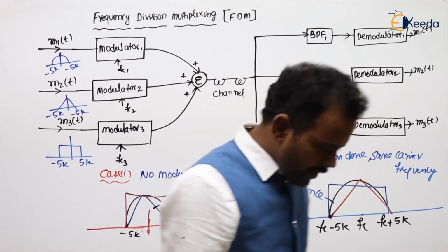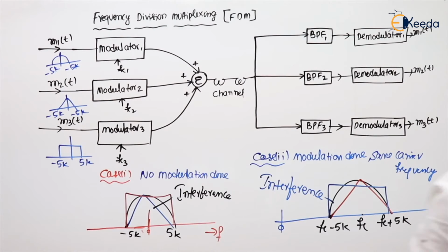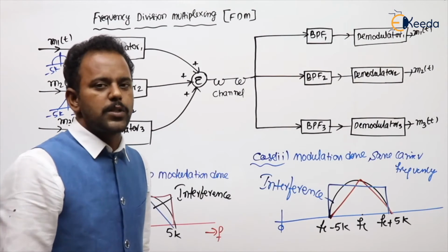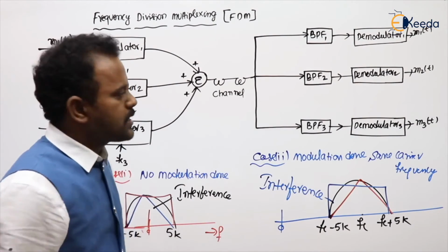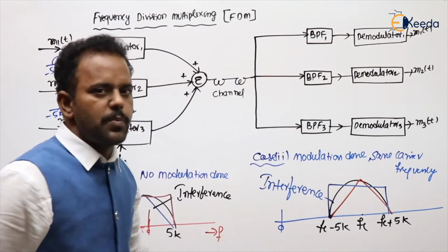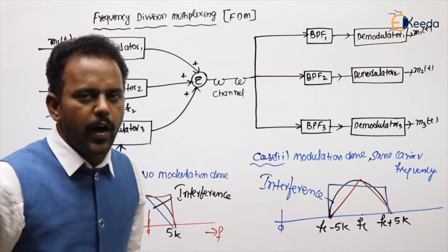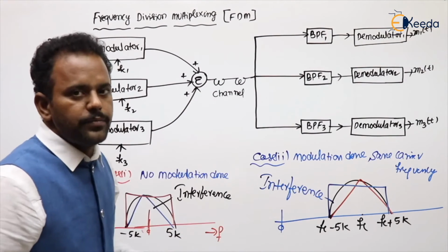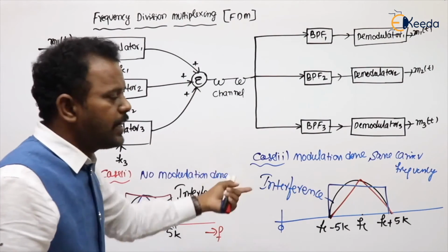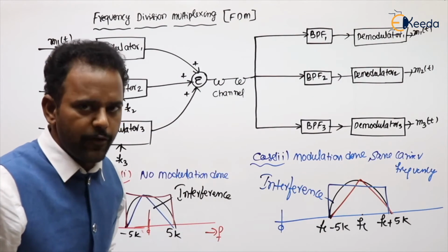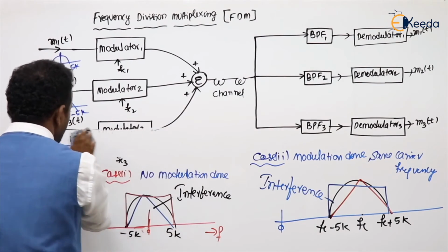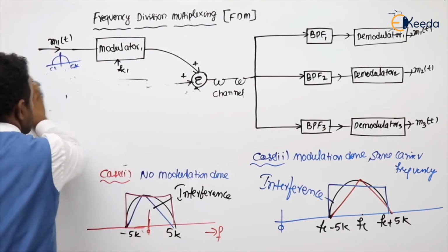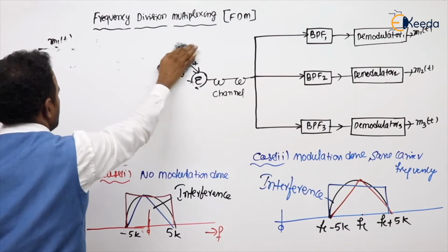So, I will take the third situation. By taking different carrier frequencies, then see how the spectrum looks, and later you will understand what the requirements of these bandpass filters are and how we have to take the carrier frequencies to avoid the undesired components from the BPF, bandpass filters. So I am erasing this to make space on the board.